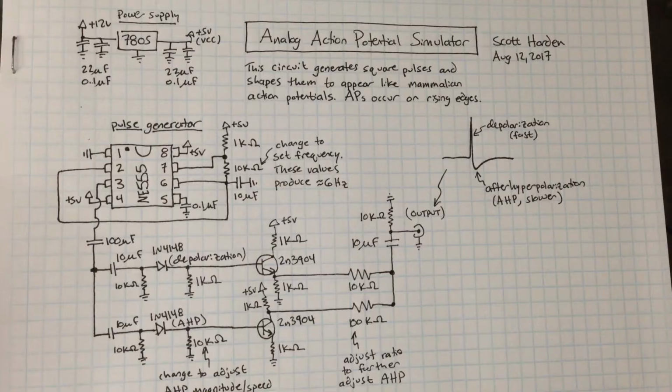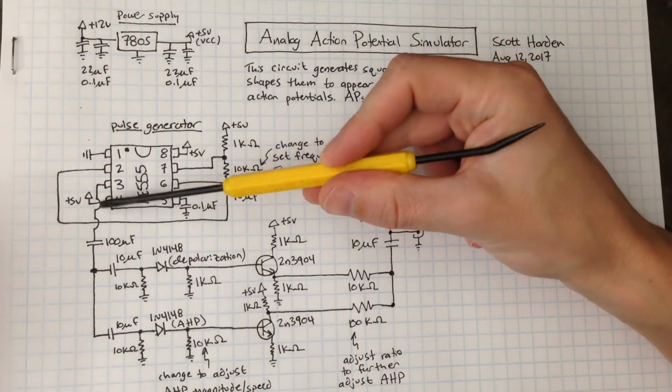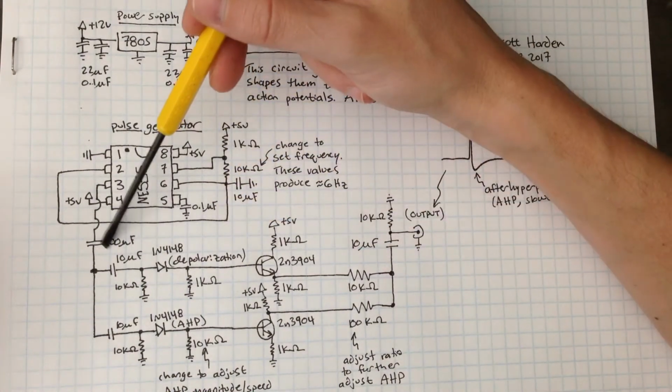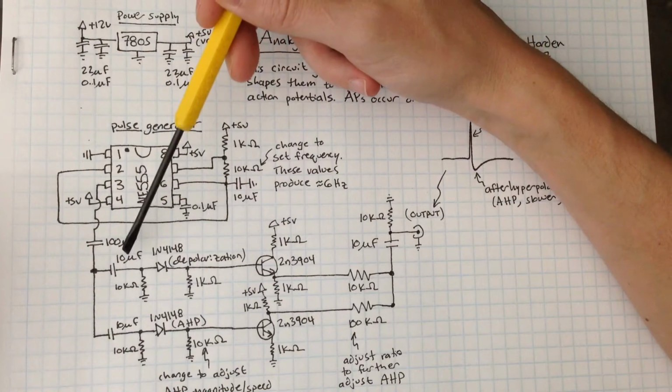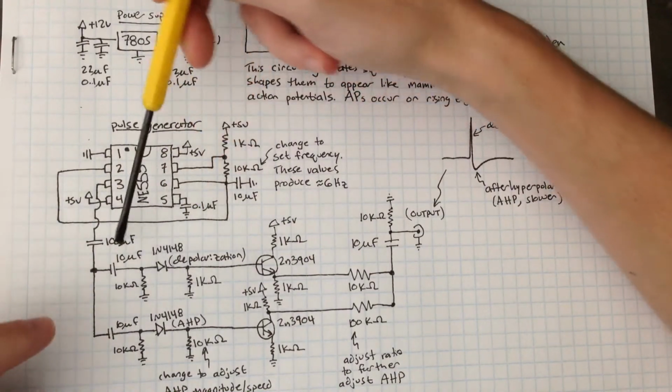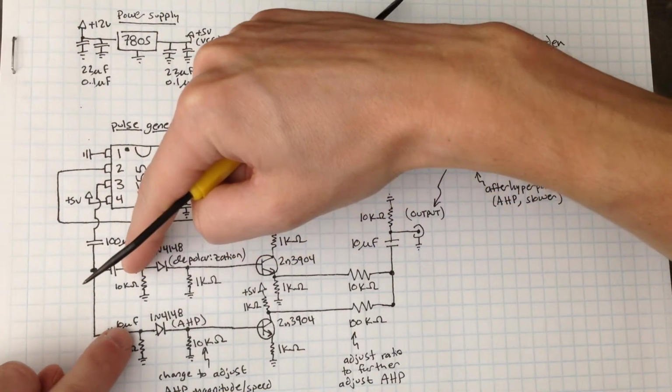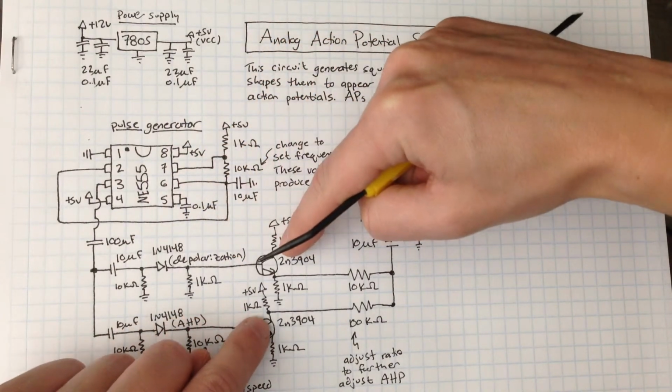So let's take a look at that. We've got square waves coming out here, and then they're decoupled through a series capacitor, and then we have 2 additional series capacitors. So from this point on, we have 2 separate signals which are handled differently.